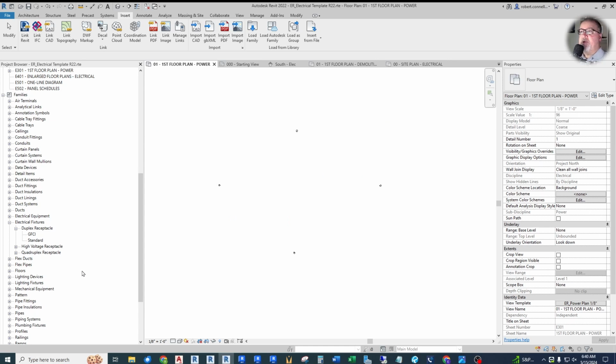for some equipment connections. I use a customized motor electrical connection and a customized equipment, like a heater, non-motor type electrical connection. Revit has some built-in connectors that you can use, but let me bring in my custom ones. But even in the beginning, I really felt like I had to do some custom content. I used out of the box as much as I could, but you'll find that, for the look of your project and for the functionality of the project, you'll need to have some custom content. And I show how to make these in videos. So let me just get those loaded.